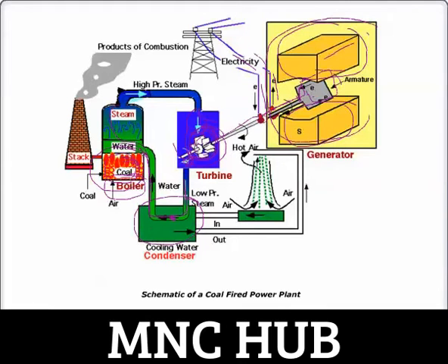And obviously when we turn the steam into water, that energy goes into this cooling water, and this water turns into warm water, and this warm water is again sent all the way up to this cooling tower. The purpose of this cooling tower is to cool the water that is condensing the steam.